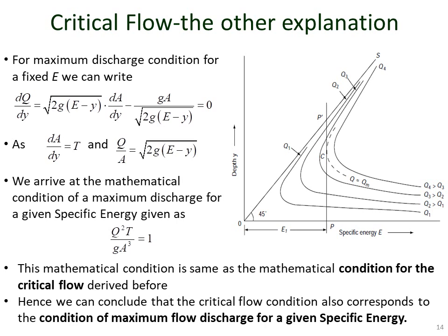So this is the same mathematical condition we derived before, and it is the condition of critical flow. Hence, the critical flow conditions can be explained from another point of view, and we can conclude that the critical flow condition corresponds to the condition of maximum flow discharge for a given specific energy.